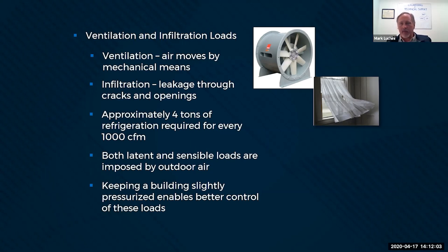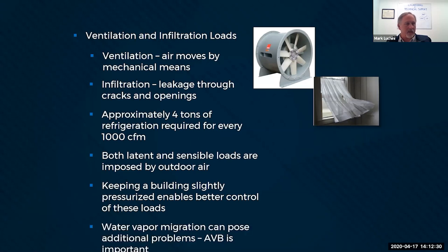We've all seen masonry buildings with the lime leaching out of the mortar. The building is overpressurized, and the AVB is really not keeping that vapor inside the building. It's letting it leak through, or it just wasn't done properly. You're essentially forcing moisture through the brick, and it's leaching out the salts from the mortar and staining the building. So for that reason, obviously, AVB becomes very important. And I got to fix that slide, don't I?